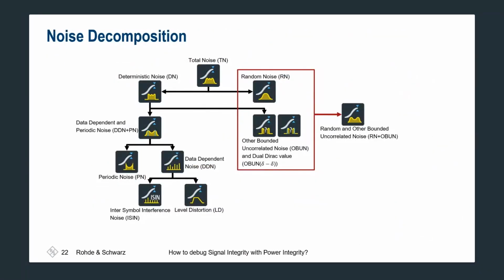As data rates and slew rates increase, the resulting bandwidth increases, and thus also the resulting noise in the DUT. Therefore, separation into pure timing and noise effects is becoming more important nowadays than it was in the past. Here we are splitting the total noise inside the signal also into random and deterministic components.